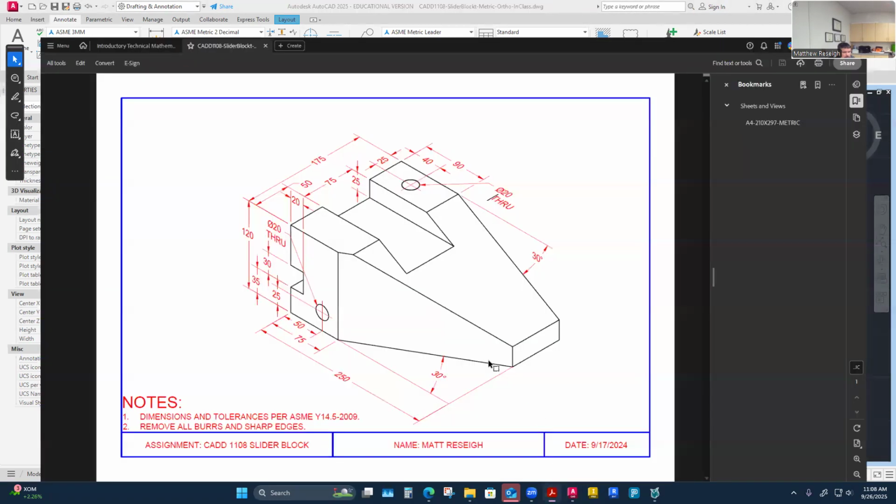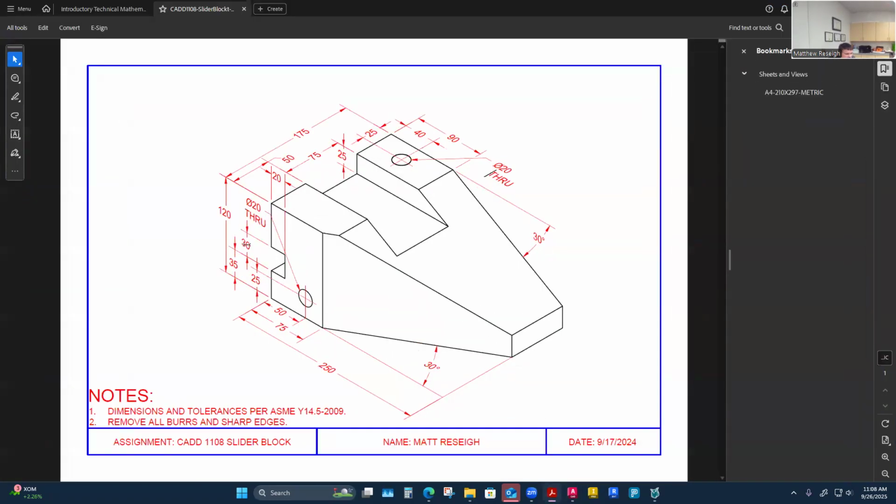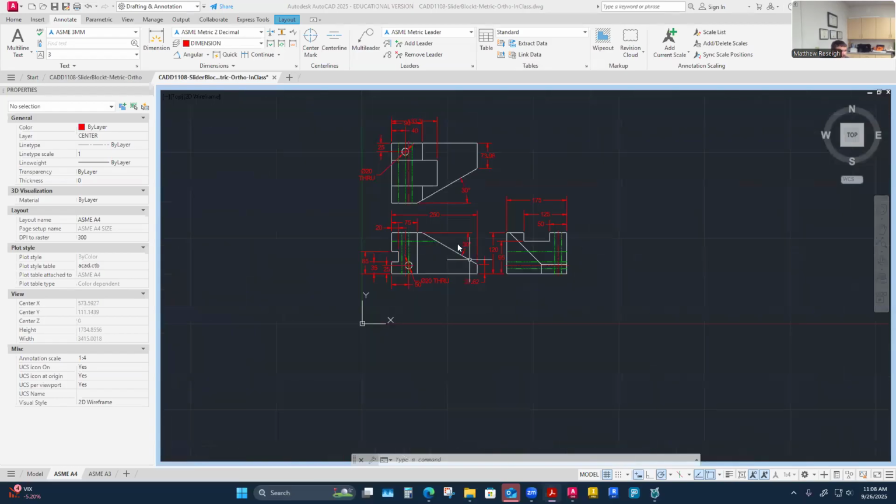Yeah, that's a good point. You could bring this up and feel like, have I done all these? I've maybe changed that one from 30 to a different one from bottom up. And then I've got the 120, and I've got that 20 in. The 50s I'm accounting for in the right side view. The 25 down I changed to come off the bottom. The 75 I didn't put in because it's potentially a reference dimension, so I pulled it from point to point across the right side view. So I definitely have all these accounted for, and I just slightly modified them for better control.